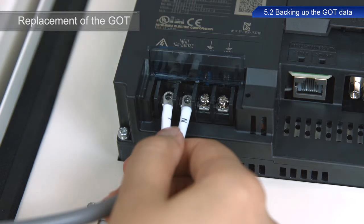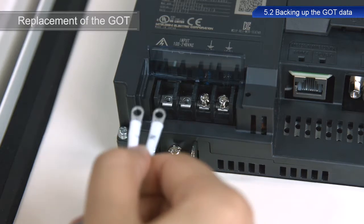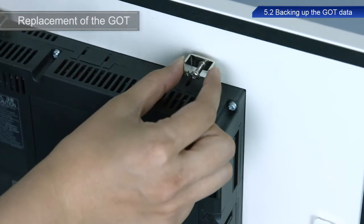For power cables, use these kinds of round crimped terminals with insulating sleeves to prevent short circuits from happening as a result of screws becoming loose. The GOT is secured to the panel with mounting brackets. Remove the brackets to remove the GOT device.